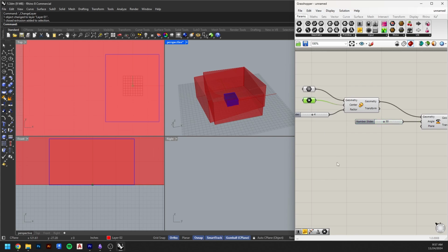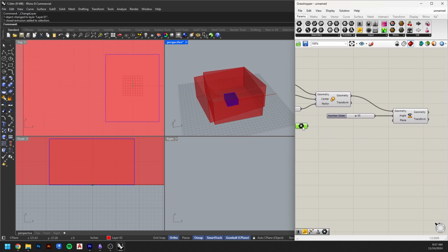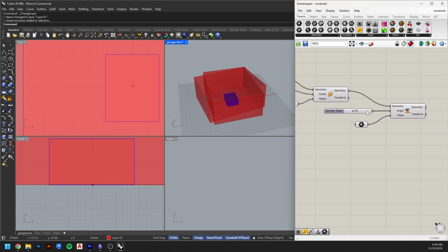So I'm going to take this node. And I'm going to copy, Control-C. Paste, Control V. There we go. I now have another node that's the container holding the same point. Both of these are holding that same point that's inside of Rhino. So let's bring this over here and let's go. Aha. Looks like it was already by default at 0, 0. That's handy. So watch what happens when I rotate my box. Whoa, I'm rotating it all these degrees.